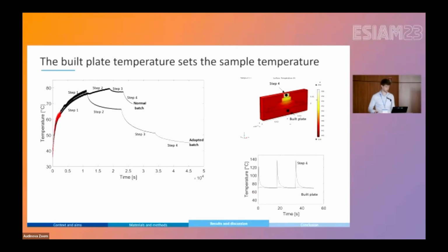So this is not so surprising, but now we know that the substrate temperature we see in the Rosenthal equation is actually our build plate temperature, which is also the build-up temperature. And now we understand why we have such differences in the roughness, in the thickness, in the porosity of our samples. As this temperature is moving, even though the process parameters are not moving, the melt pool of our sample will also be modified.